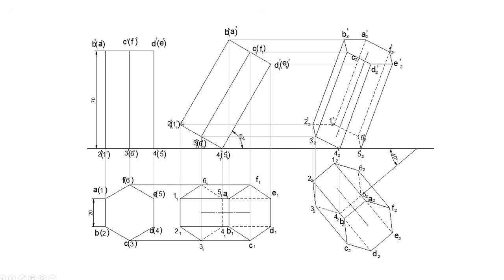Now you want to consider the points which are coming inside brackets in this diagram. So here we have 1, 6 and 5. So all those lines, the remaining lines to those points, will be invisible. So 1, all the lines will be invisible. 6 also, all the lines will be invisible. But 5, you already marked this as a border, so the border will be visible. So that means from 1 you have 3 lines invisible, and from 6 you have the remaining 3 lines invisible. And all other lines will be visible. So in that way you can mark the visible lines and invisible lines here.